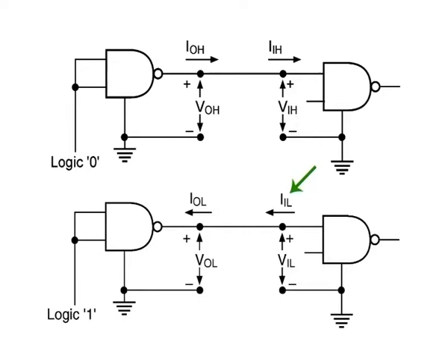In the case of bipolar logic families such as TTL, the circuit design is such that the current flows out of the input pin and is therefore specified as negative. In the case of CMOS logic families, it could be either positive or negative. In this case, only an absolute value is specified.